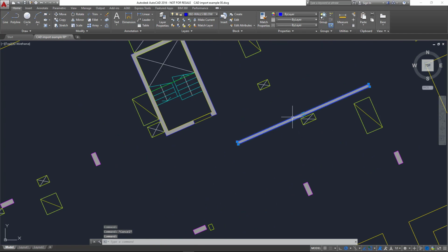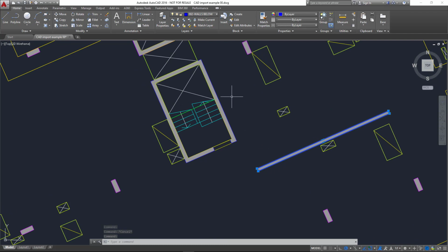Similarly, walls are drawn with a single closed-form polyline wrapping around their entire perimeter. Even for walls such as the shear core, we draw one polyline wrapping around its perimeter. In this case, the software will use the two parallel lines running along the wall's length to determine the wall's length and thickness. Alternatively, I could have drawn a single line through the center line of the wall, and the software could use that line to import the wall.